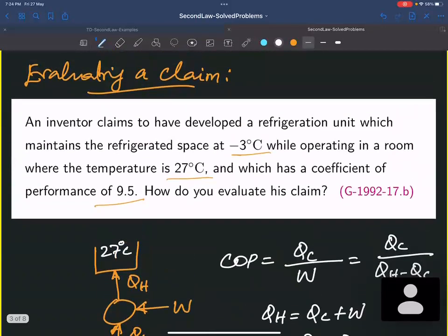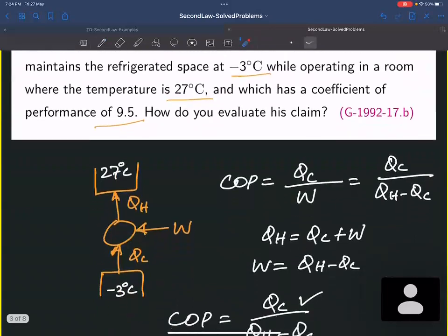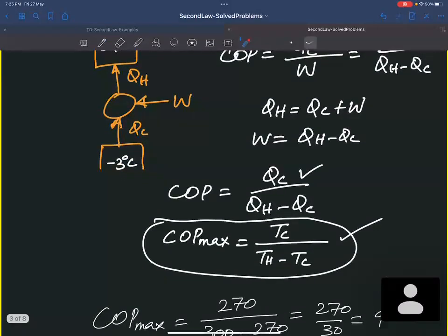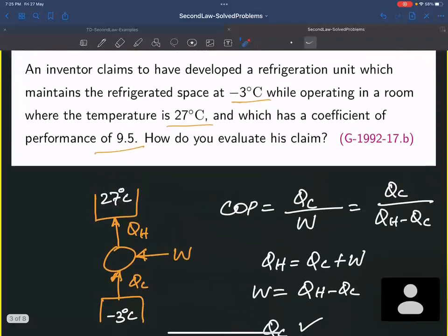So we are simply doing the claim evaluation based on Carnot. The maximum efficiency of the engine is given by Carnot, or the maximum performance is given by the Carnot refrigerator. So simply find the efficiency or COP from the Carnot formula, which deals with temperature. It is enough to know the lowest and highest temperature. With that, we can find the COP or efficiency, and from that evaluation, we can say about the feasibility of any process.